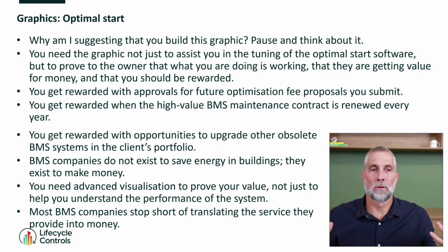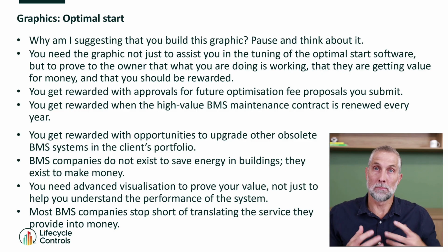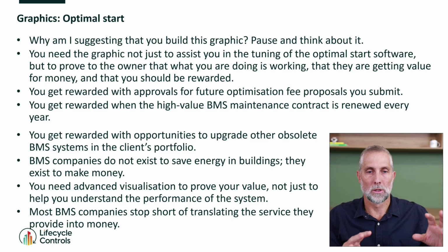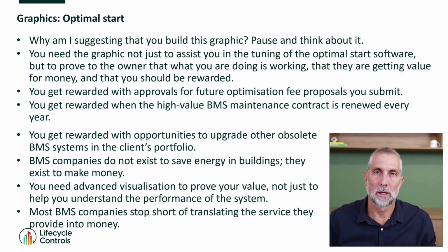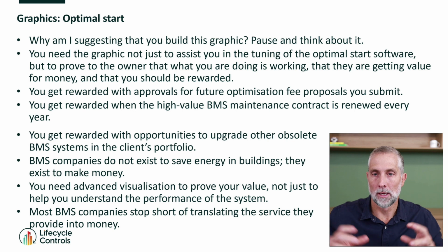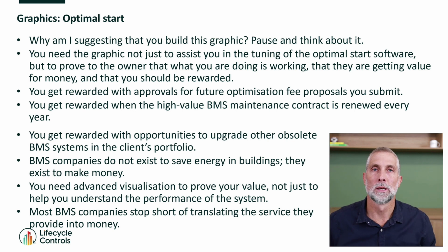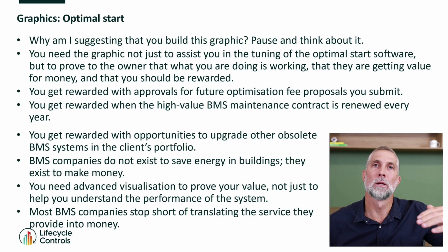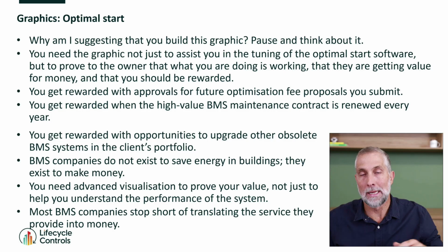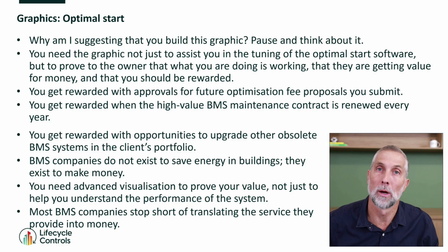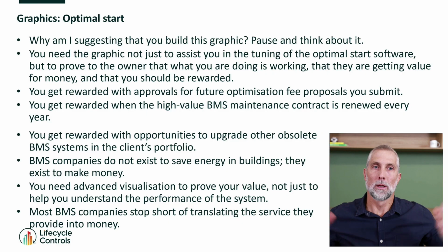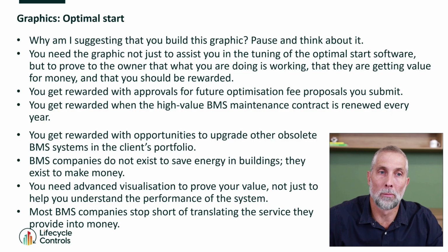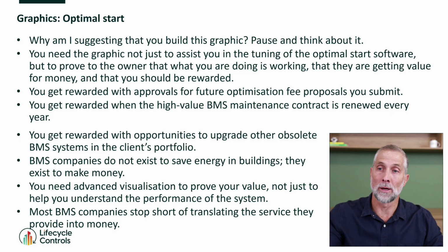And then if I was a very mean person and I said to you in that meeting with the customer, okay, well, show me your air handling supply pressure reset and your temperature reset, and show me the analysis around the optimization of how cold that supply air should be to save energy, keeping in mind it's using more chiller pumping power. Wow. Okay, that's an exaggerated example of a very complicated thing. I would never ask somebody that question in real life because it would be so mean to ask.